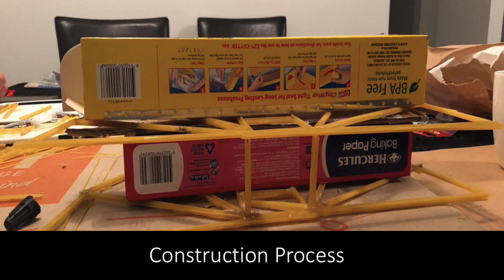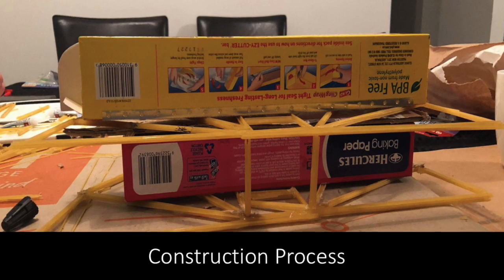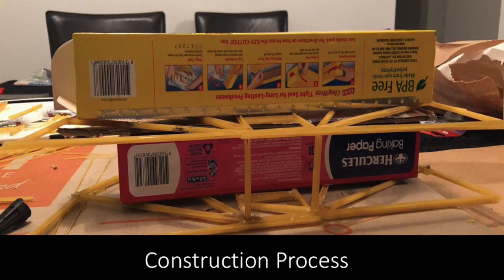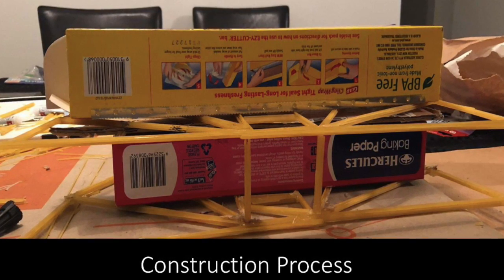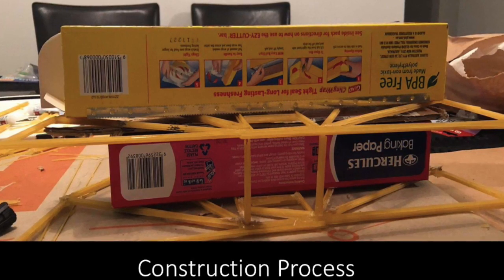Assembling the beams into place started by gluing the bottom long beam together, which overlapped to add strength. The inside beams were then placed and glued. Once these had both dried, the outside small beams were cut using a sharp knife and snapping technique to stop the spaghetti from cracking. The beams were cut to fit into the circular outer and glued in. All these steps were then repeated to create the second frame.